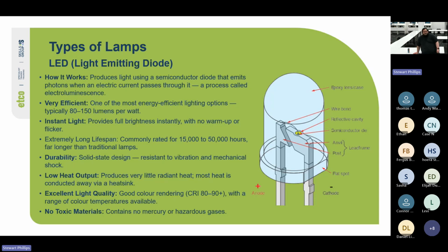Has anyone ever experienced an LED flickering before? Was it constantly? Was it strobing on, off, or was it a very quick kind of rapid flicker? Strobing? Okay, so what that means most likely is that the capacitor has blown.